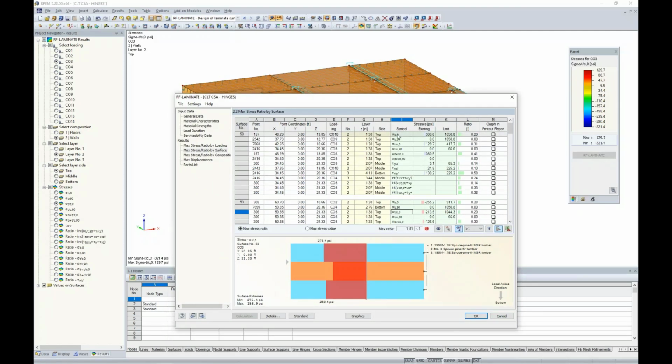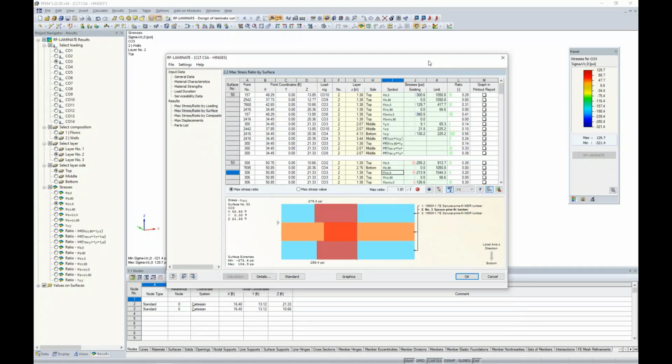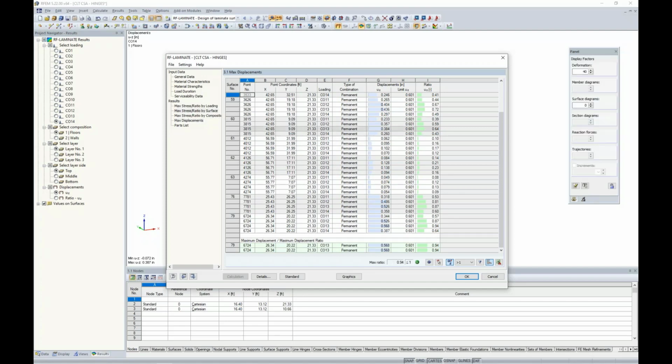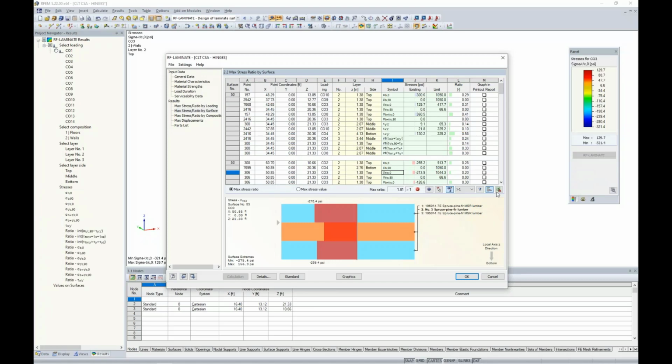And within each surface, as I mentioned, we're going to be checking bending, tension, compression, combined interactions here, shear, as well as torsion for our walls, and ultimately coming up with a design ratio. We also have the max displacements here. So this is our serviceability checks. And remember, we are running in comparison the deflections to L over 360, we will get a max ratio here as well.